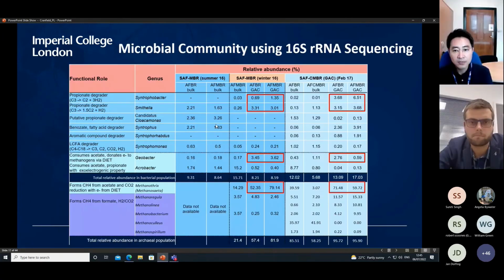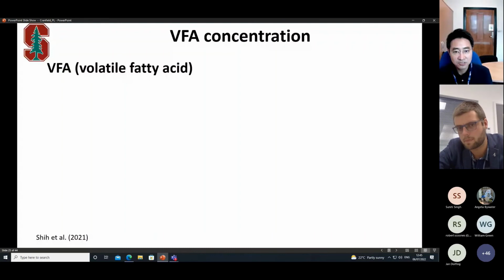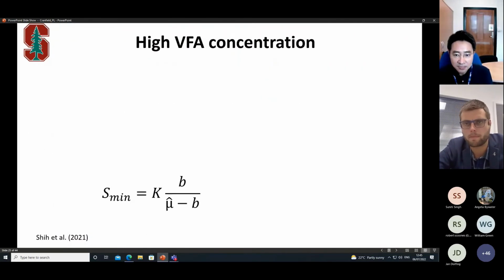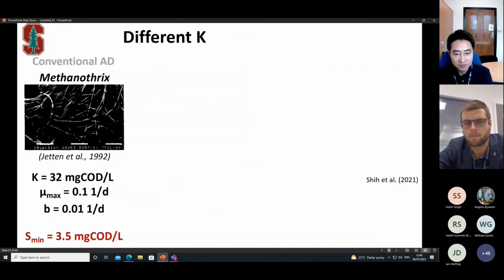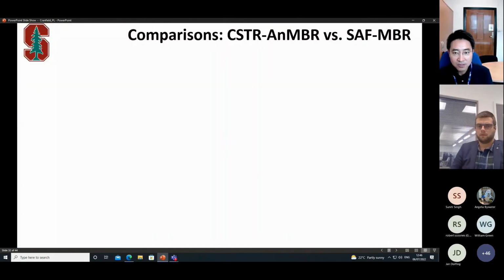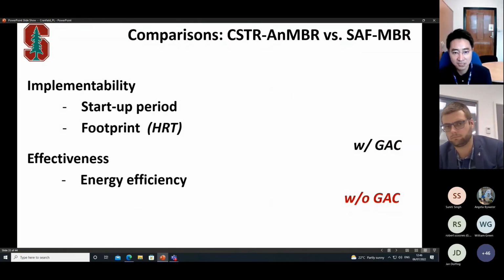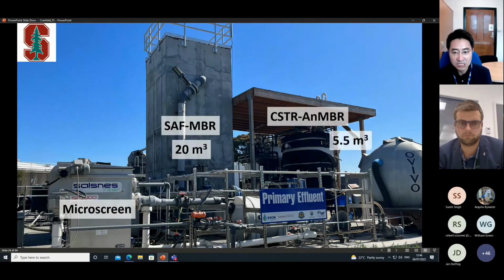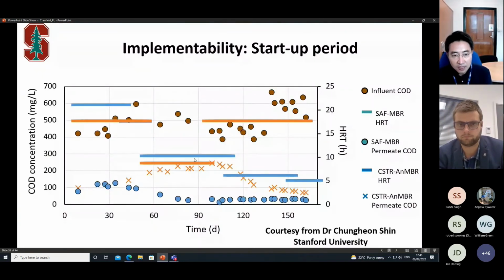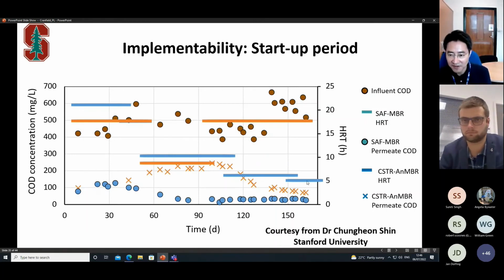No, no. For example, in the pilot scale we use a 5-hour HRT, so it's fixed, and you can see the influent is variable all the time. I'm going to get to the slide very quickly. Sorry about this. So we have these three different periods of the pilot scale. We always fix the HRT. In the beginning it's a bit long HRT because we want to grow the biofilms, but then after probably 3-4 months we can hit about 5 hours.